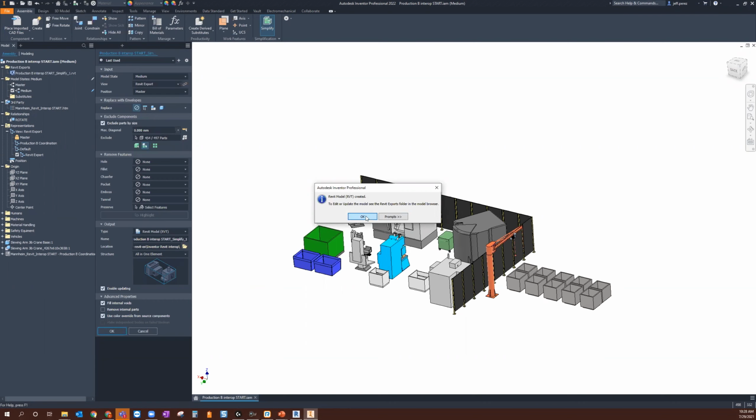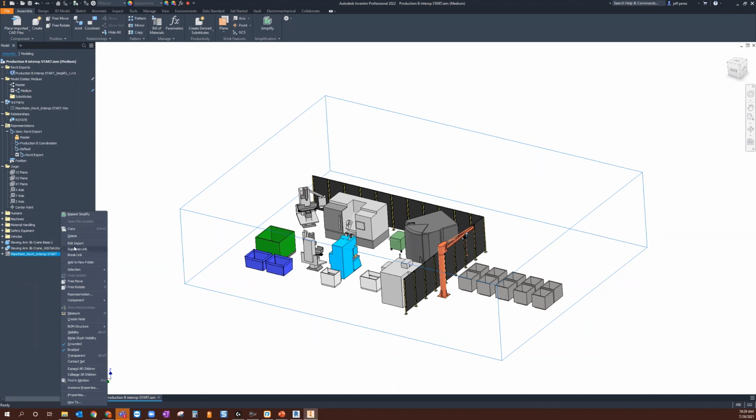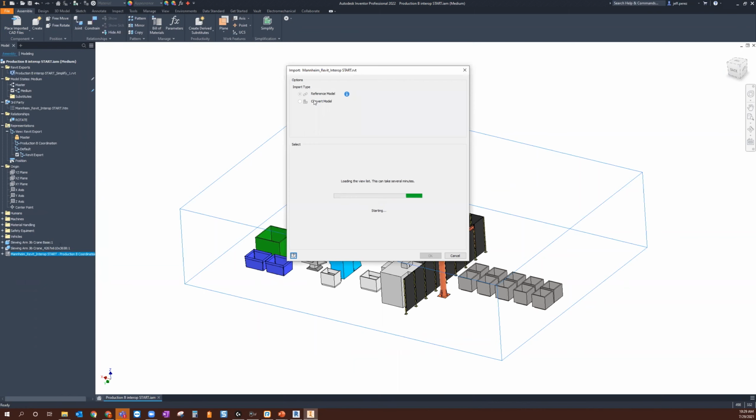Now we'll just confirm this. As I mentioned, we should see a Revit export folder up here. And there it is. There's that file name that I determined. And as Adam was asking, can we ever go back to that imported Revit file and update some of the categories that are being brought in? We can. We're just going to select that file that we brought in. We can right click it, and then we can edit the import, and you'll go right back into your AnyCAD import. Then you can deselect or reselect any categories that you may have turned off, or you can even reassociate it with another view that you may have created. Okay, so you could always go back and edit these.